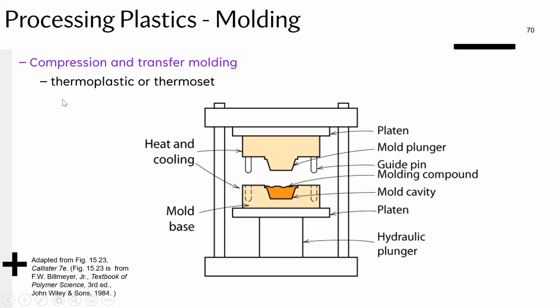If you've got a thermoplastic, you can also have it polymerized and then reverse it here into a different polymeric object. If it's a thermoset, this has to be a monomer that you put here, and then you cross-link it. Now it's permanently, forever made into a polymer structure. And beyond that point, you cannot reuse it in this process. So that's the difference, okay?